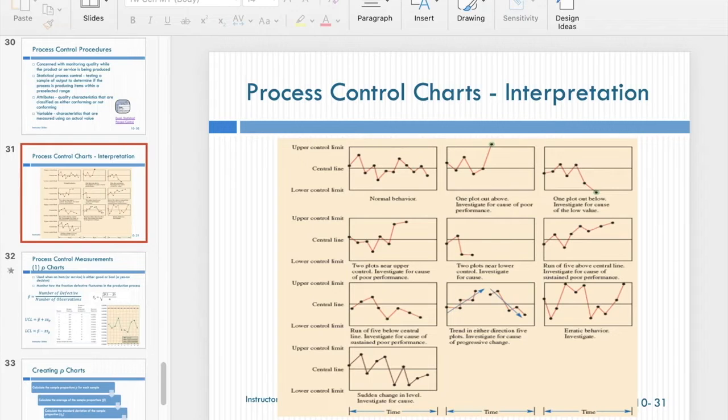So you have to monitor very closely, because under this situation, this is already a signal. Maybe it's not as severe as this one, but it shows a signal. And for this one, it's decreasing and very near the lower control limit. So you also see a signal that you have to monitor carefully.